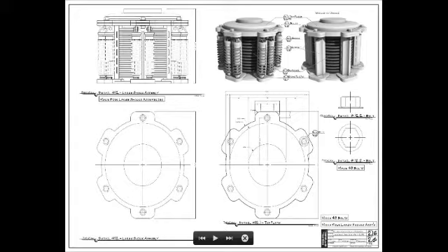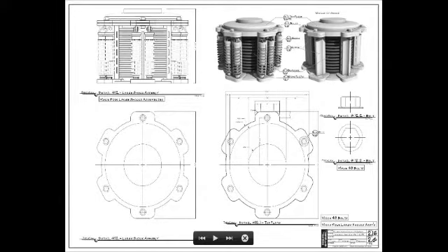The nice thing about the new version is that because it's linked to the model, if you modify the model, it will modify the drawings as well. Matt, you can correct me, I don't do too much of it currently, but dimensions and things like that, if they're associated, will adjust as well. If they're not associated, then you can go in and adjust as you need to. But it's a real time saver, the automated process.